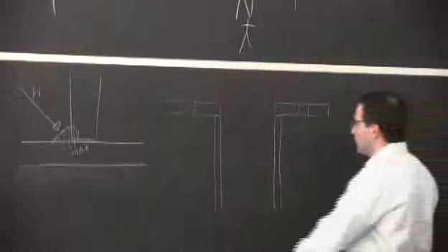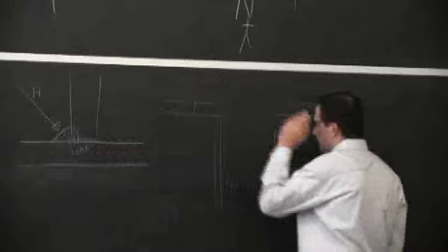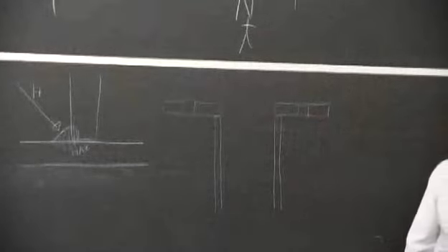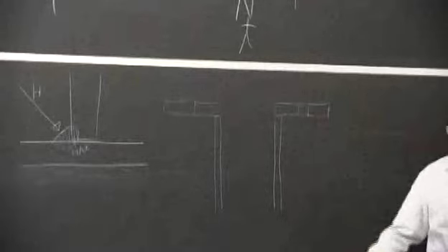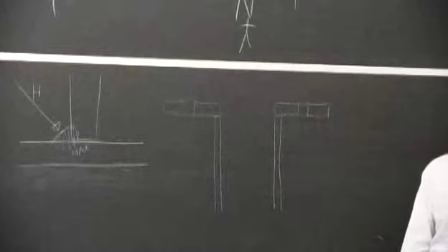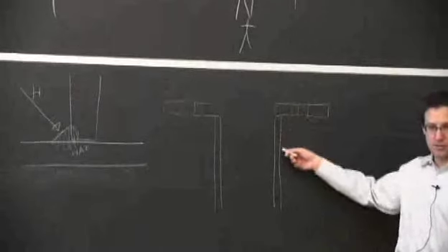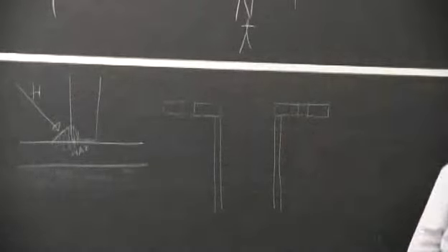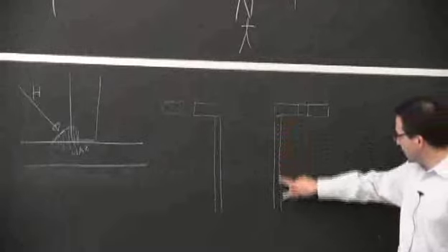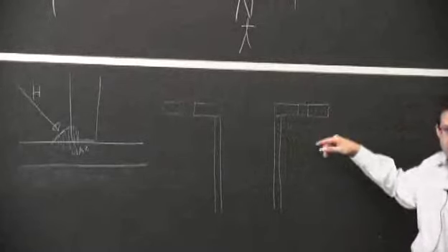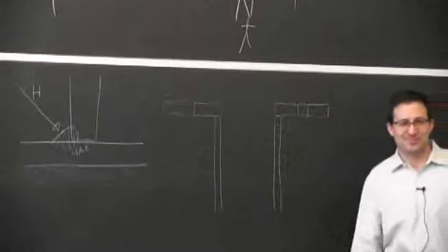It's a little bit the same way as here, where these are two pieces of metal. I think you realize now that we just can't cast everything. We'll do it sometime. We'll use ductile iron to make these as a single piece, the flange with the pipe. But it has a lot of limitations in terms of properties, and it's expensive to do. So the cheapest way is really normally to make a cylinder, make that flange, and then you want to weld them together.